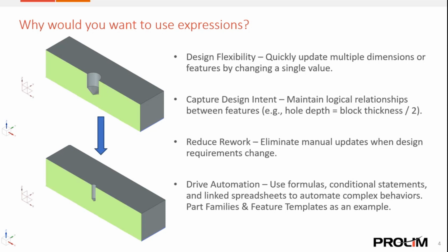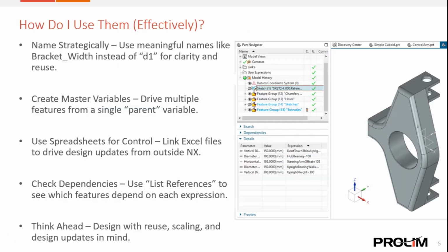And when you're working in complex assemblies or even the reuse library, expressions make your parts scalable and adaptable without any extra effort. And you can also use expressions to drive part families or feature templates, and I'll show you an example of a feature template later on in the demo.